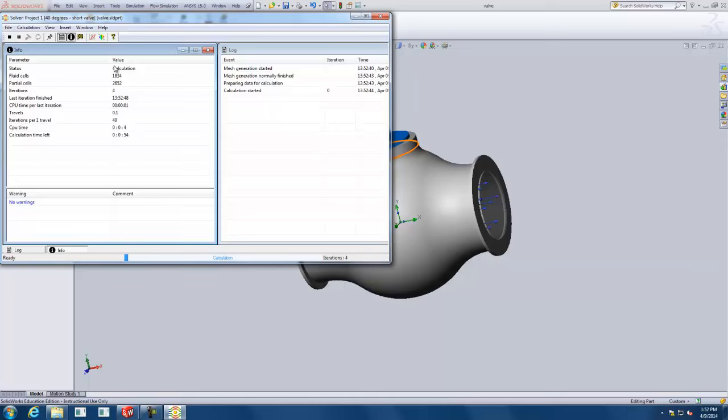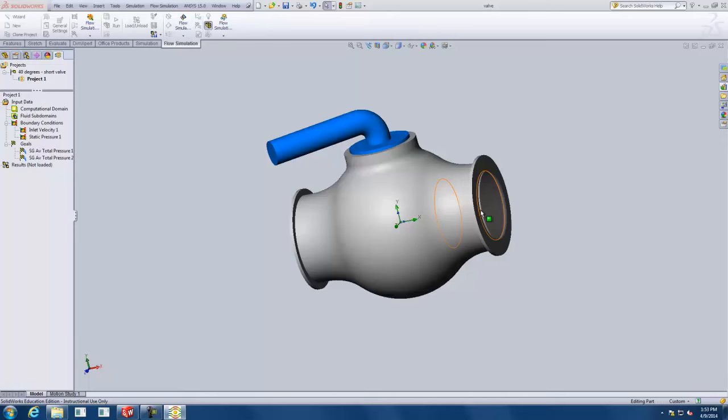You can follow along what it's doing right here. You can follow calculation progress over here. And this is going to pop up here. It says the vortex crosses the pressure opening. All right, so we have the pressures here, and it says there's some type of vortex going in and out of this pressure opening. We don't have constant flow exiting out at that point. It's a vortex, and that is not a good place to be in your modeling.